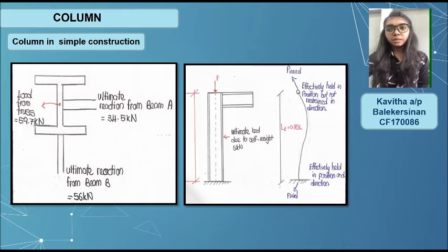In simple construction, members are connected by normally pin joints and horizontal forces are restricted by bracing. Beams connected to the column face usually induce a small bending moment due to eccentric application of the transfer force. Beams are connected to the column by means of simple construction.